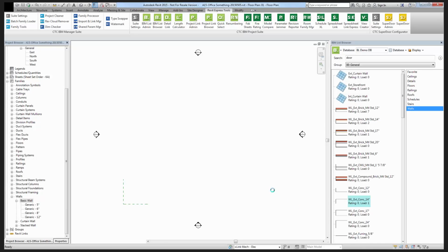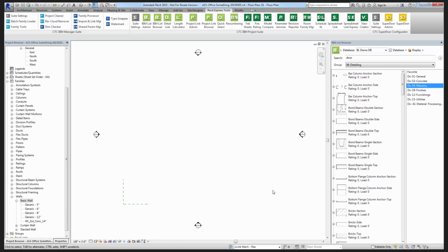And yeah, it might take it a second to go ahead and do that, but as an end user, I didn't just spend 10 minutes going to look for the right project file to open it up, detached, making sure I don't mess it up, and then doing transfer project standards and waiting another 5 minutes. It took it 20 seconds, and it brings in my wall type. So it's still pretty quick because it does have to access that external file, but it brings it across very quickly. And now I've got it right here, and I can begin drawing that wall type directly in my project.